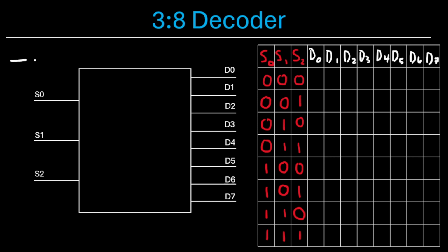Here you've got our last decoder, a 3 to 8. We've got 3 input bits, S0 being the rightmost, S1, and then S2 being the leftmost. And again, we can represent numbers 0, 0, 0 through 1, 1, 1, or 0 through 7. And you can see that reflected on the decimal outputs, D0 through D7. Okay, so if we input 0, 0, 0, or binary 0, the D0 pin should be on, and all the other pins should be off.